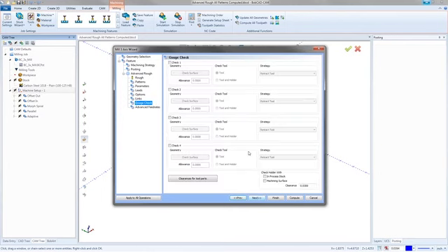Gouge checking. Really, with gouge checking, I don't mess with it until I see that there's a problem. When I watch my simulation, if I see a gouge and I see that the easiest way to fix that gouge is to go into the toolpath and pick some geometry to tell it to avoid, then I'll do that. But if I don't have any frame of reference, really, I don't know if this is going to gouge yet until I watch it in the simulation. So I'm not going to set up a gouge check right now, but it is definitely something we can come back and add in later, especially with this toolpath with the ability to do in-process stock.